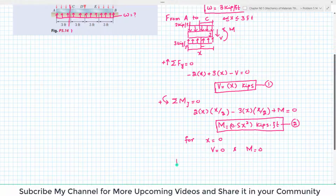Now for x equal to 3 feet, or we can say at C minus, this is point C, clear. So for x equal to 3 feet, you can put it over here, so V will be equal to 3 kips, and the moment will be equal to 0.5 into 3 square. 3 square is 9, and when it is multiplied by 0.5, it will be equal to 4.5. So 4.5 kips into feet.